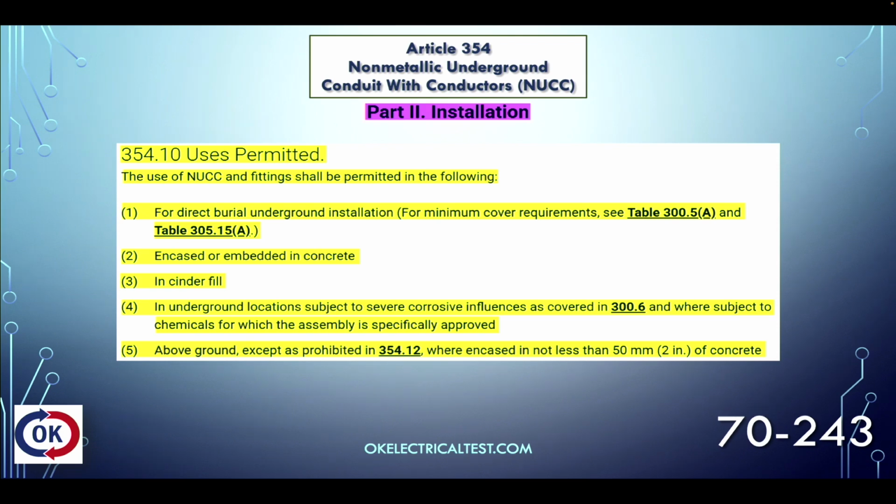And 300.6, if you remember, that's protection from physical damage, and we're subject to chemicals. Number five, above ground. So we can use this in corrosive conditions. We can use this for direct burial. We can use this above ground where it's encased in not less than 2 inches of concrete. Okay? So a lot of different applications we can use for this nonmetallic underground conduit.